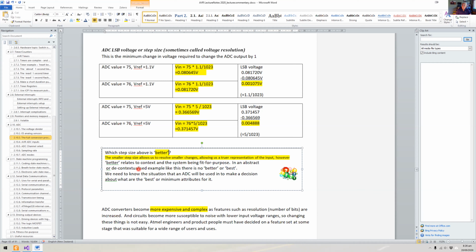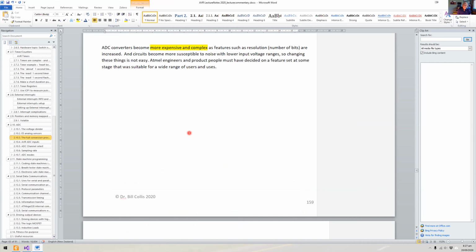If you need something more complex than that, then there are more complex analog to digital converters around. For instance, even the ESP32 that was used in 101 and promoted there as a sort of intro to microcontrollers generally, it had a 12-bit ADC. And you can buy ADCs which are 16-bit. So there's all sorts of things available. It's just a matter, again, of understanding what it is you're thinking about using it for and understanding the limitations of what you can do with your system. That's engineering coming down here.